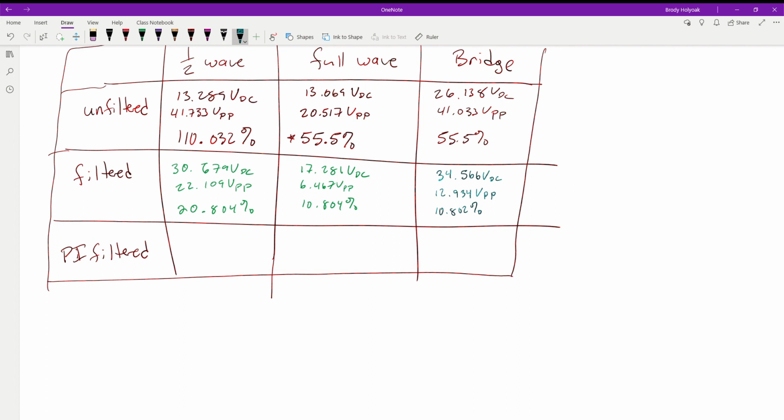But either way, like I said, this is just understanding the basics. The other things you just keep in mind as you're going through these and designing. You're like, well, why is this? How can I change things? And that's the biggest thing too: this is not the only way to look at these circuits. This is just an example of the basics of what you can do. You can start going through and say, okay, I want my DC to be a little bit higher. So what I need to do is increase my minimum voltage, so it comes up closer to my maximum, so the average goes up.